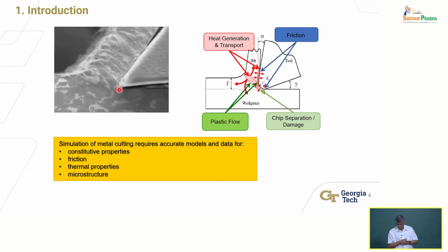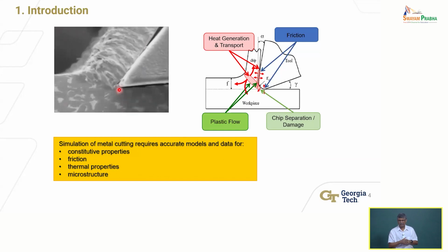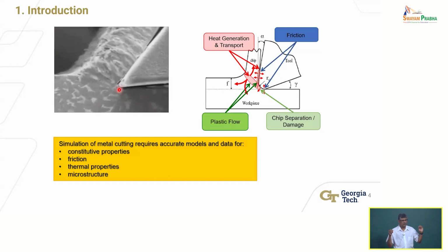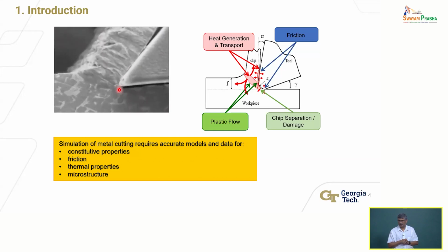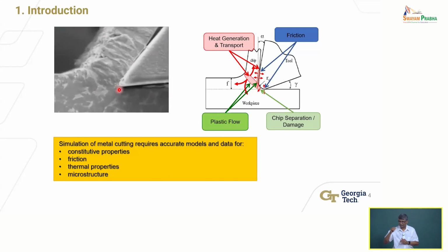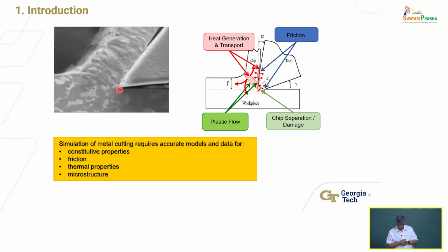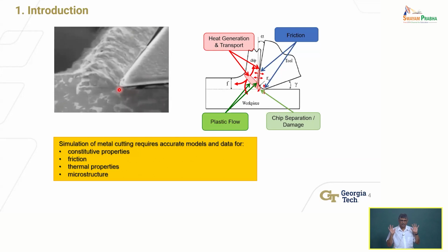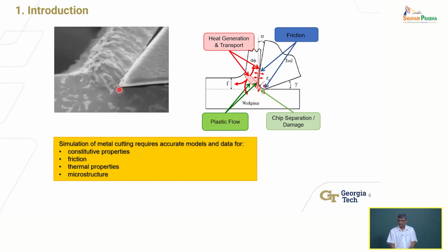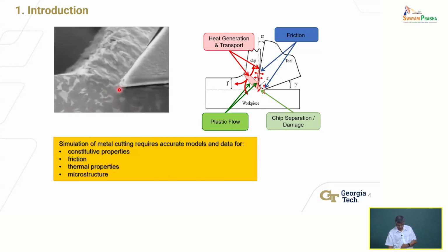In a typical tension test, for a ductile material, you're talking of strains probably on the order of 0.4, 0.5, 0.6, depending on the ductility, not 2, 3, 4, 5, nothing like that. So, much higher strains. As simple as the process looks from the outside, what's going on inside is very complicated. That's what makes it difficult to model.